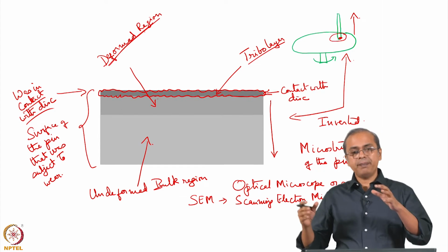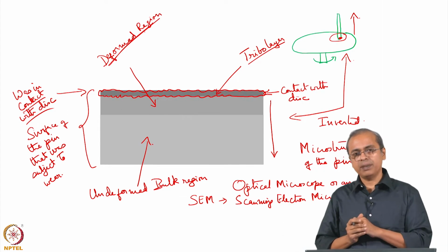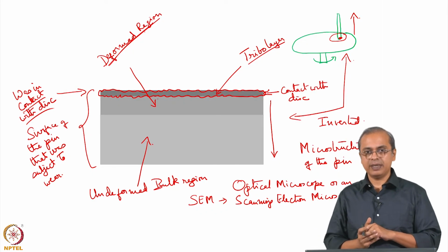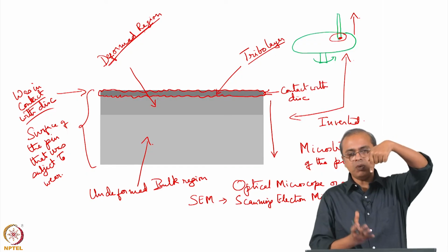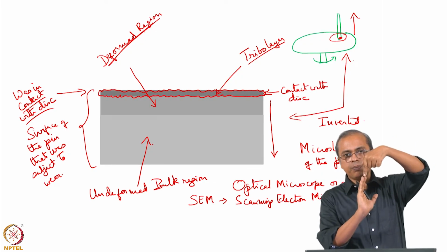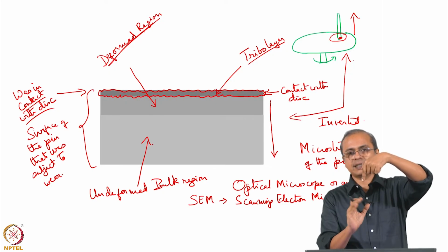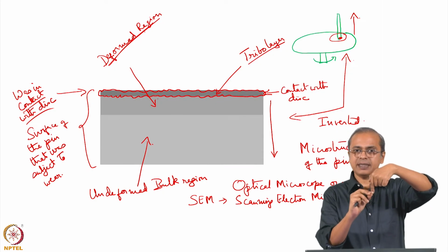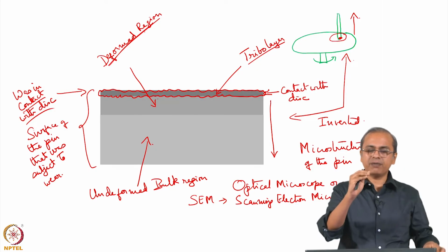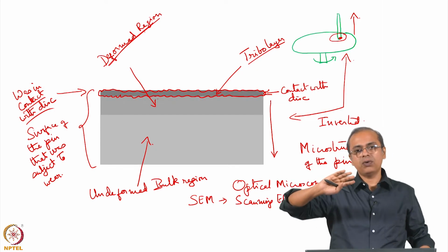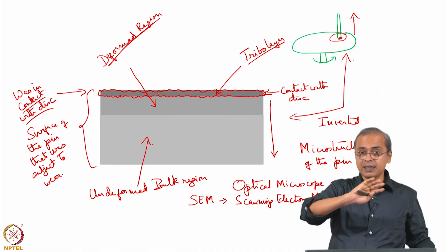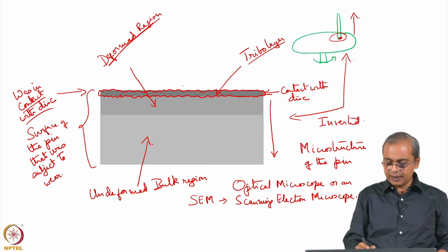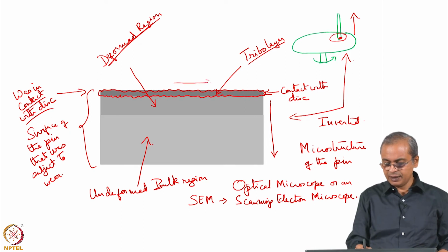and that is because of the mechanical stresses that are there on the pin, because it is being subject to this test of pin on disc. So as you can imagine, with the pin down and as the disc is rotating, you are trying to push the material in one direction. So it is getting pushed tangentially. So the surface layer of the pin is getting damaged, the layer just above that surface is also getting pulled in the direction in which that disc is rotating. So let us assume that the disc was rotating in that direction, right.